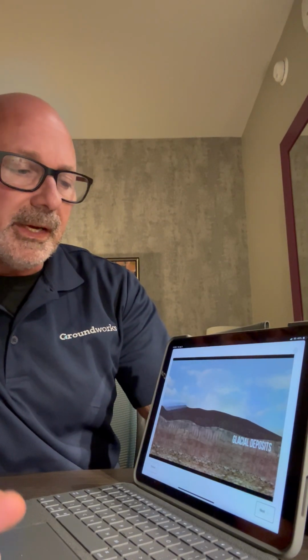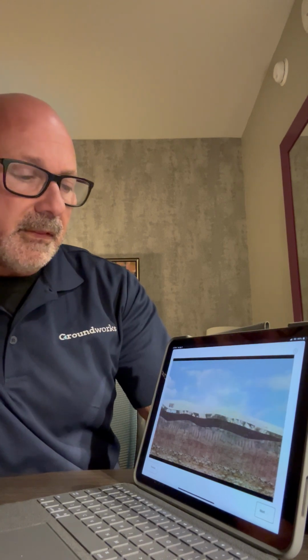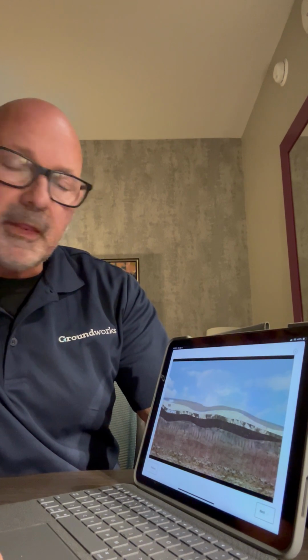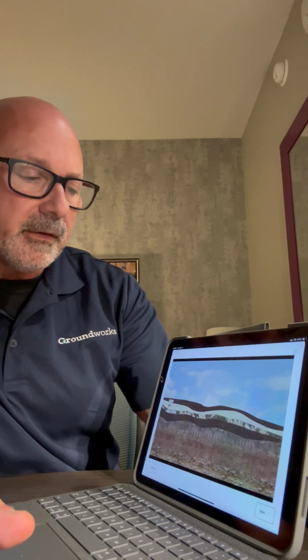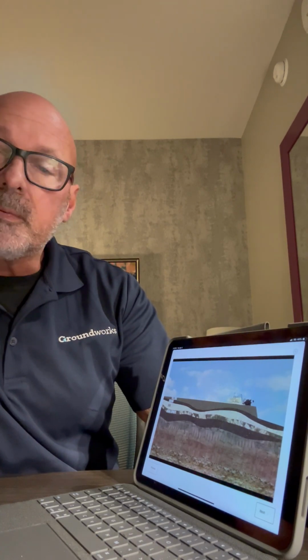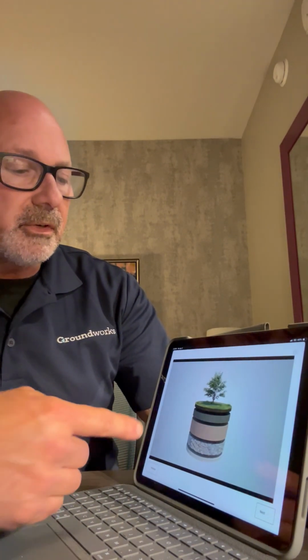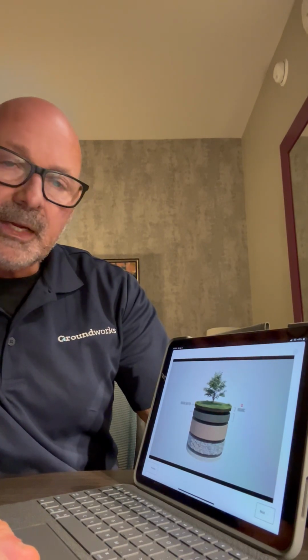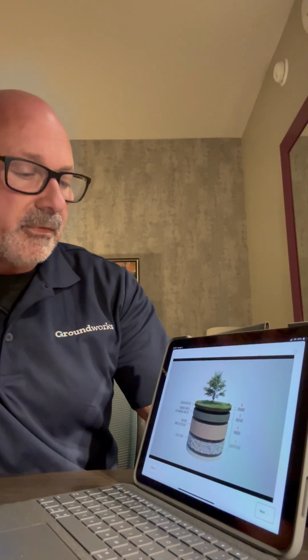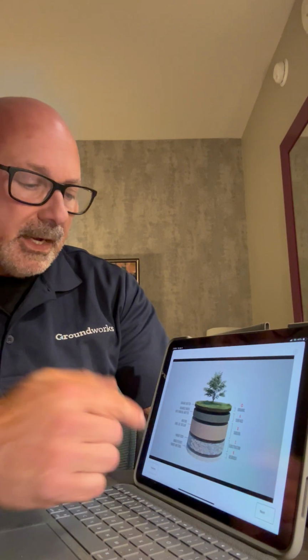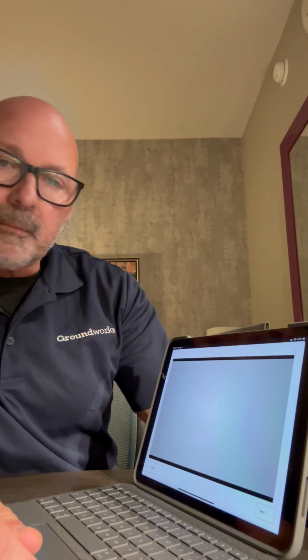We can discuss that. So first, it's important to know the different layers, right? There's glacial deposits, and then there's been wind and all kinds of weather that has affected the earth and what would be sitting underneath your house. And then, of course, we come in and we put in fill soil because it's an imperfect surface. We've tried to create a surface that's worth building on. And so you can see we've created different layers over time, and by man-made layers, right? From organic matter all the way down to basic parent rock or bedrock, right?